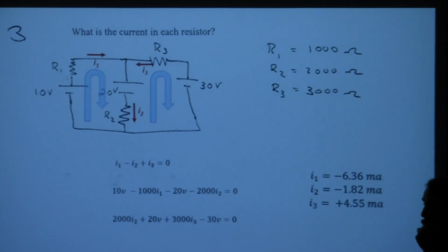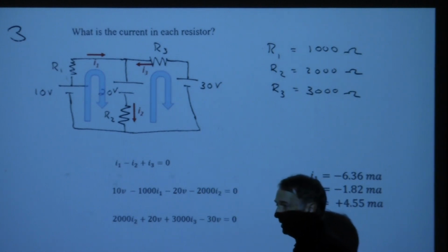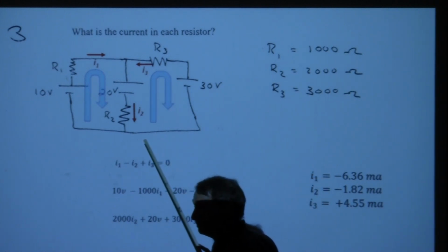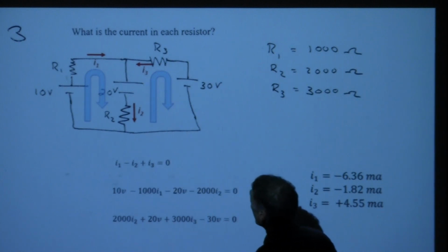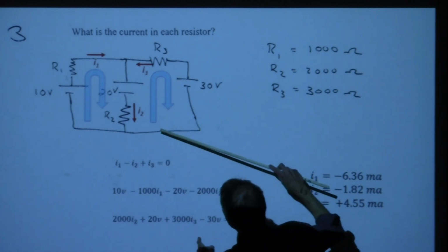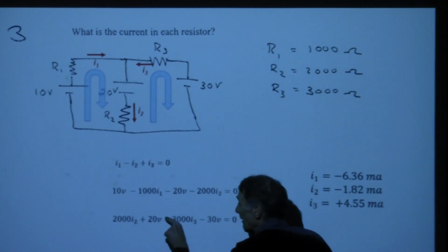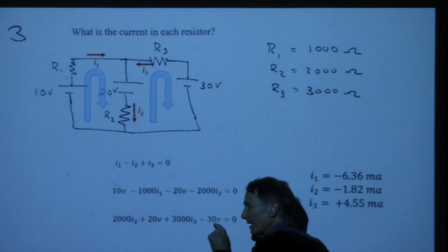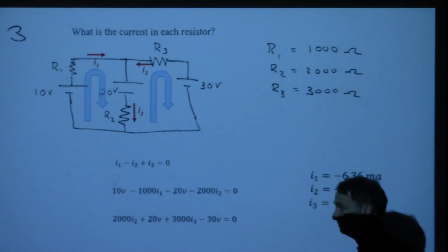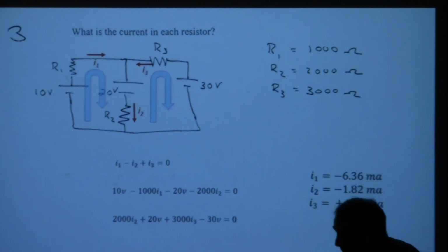Yeah? Why do we draw loops in the same direction? So one clockwise, second. Okay, I just happened to do it here. And you don't have to. You can go the other direction. Let's say this second loop, we're going to run it in reverse. You'll find that if we go the other direction, this would be a rise of 30. That would be plus. This would be a minus. All that's going to change is the sign of these. And that's it. What are the chances of me making a mistake on the exam if I decided to do it the opposite way? It works, again, just fine.